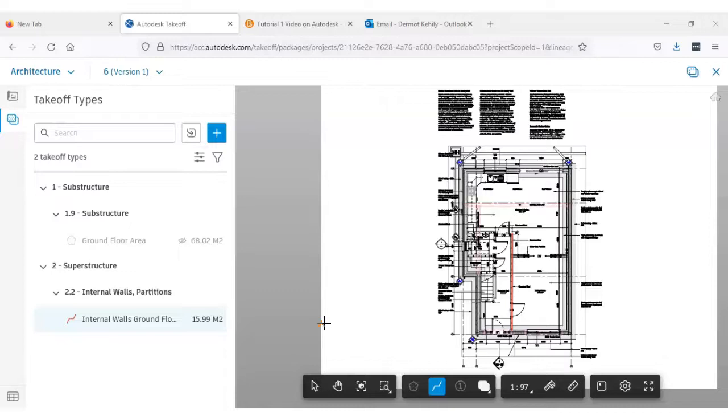The stuff you're doing with Figure in relation to building up descriptions and then using measurements within those descriptions, this is not what this does. This essentially does your raw takeoff. So you might take off your gross floor area, certain areas of different floors, or your internal walls, but those quantities then have to be used within a description. So we're not creating descriptions as such, we're just creating takeoff that we can utilize then in an actual bill of quantities description or a cost plan description somewhere down the line.